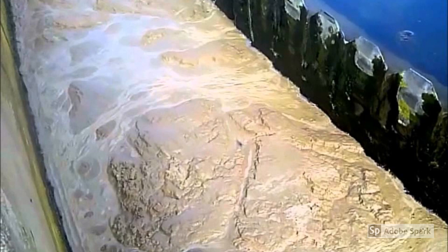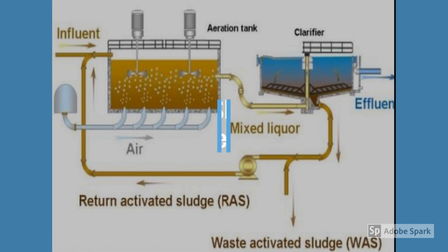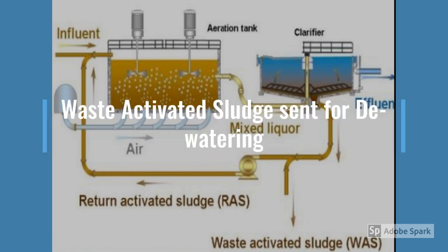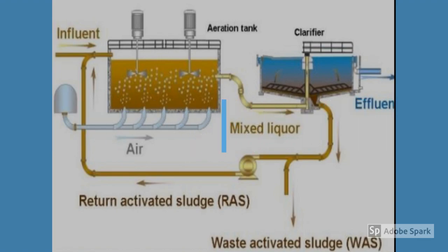As part of this process, a scum forms atop the activated sludge, which consists of filamentous waste. This is harvested at the treatment plant for disposal. At the end of this process, there exists a surplus of activated sludge that is no longer needed. This surplus activated sludge is then sent to a dewatering process via a waste activated sludge or WAS pump.